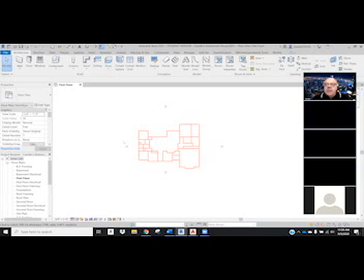Okay, so the first thing you have to do as a designer, other than the commercial students who are rebuilding the wall in 3D as it is in the 2D drawings, if you're building a house, you need to decide what to make it out of. And with the current building code, we are now looking at an R24. That's a resistance to heat change in our insulation for our walls. When I started this, we were doing an R13 back in the late 80s. That was sufficient enough. We're now up to an R24 for insulation value.